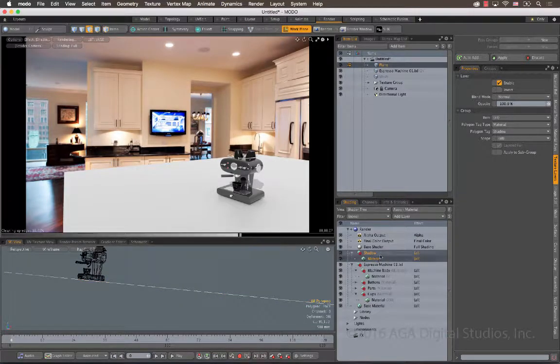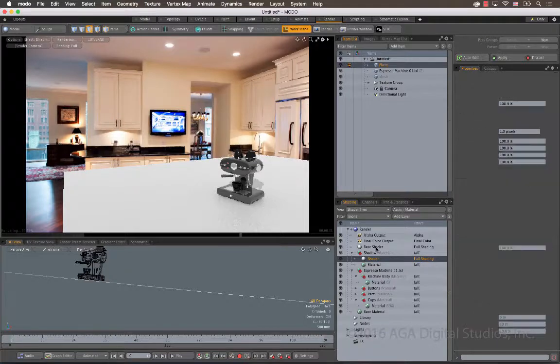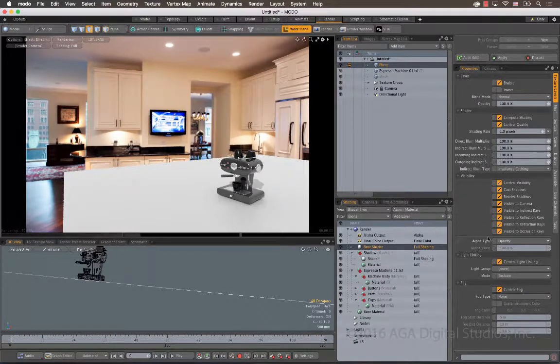Okay, so here in the shader tree for shadow, what we want to do is add under special a shader. Okay, we have our base shader here. It's the same thing. Okay, controlling our visibility, our camera, everything else. This one's going to have its own shader, and in that case, we're going to make the alpha type shadow catcher. All right, and basically what I'm telling that is only be a shadow.